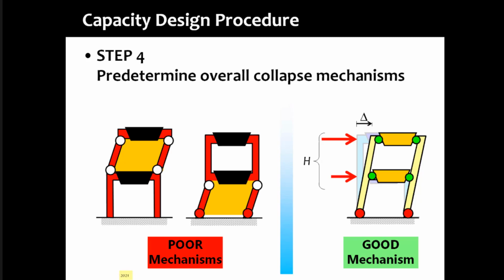So you will see if you have a two-story bridge system, you will see this column mechanism here. But it will be possible, if it is possible, that you can put this hinge in the beam segment. You may have a girder here which is very deep and stiff, but if you can make the bridge a little wider and put a beam section here and make sure that the plastic hinge happens in that beam, then you will be able to save the column from getting into shear behavior. Of course, there is a ductile hinge at the bottom here that will be necessary to make the collapse mechanism happen.